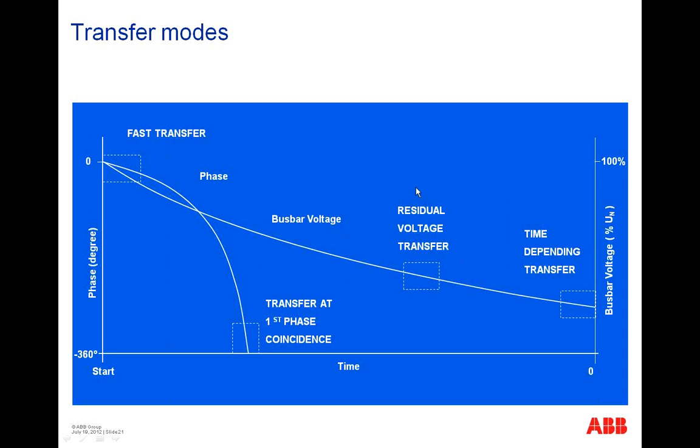At the moment the busbar is isolated, the machines are running at high speed. At this moment, they act like a generator. They are feeding energy back to the busbar while declining in speed. Both breakers are open, from the main feeder and from the standby feeder. They work as a generator, feeding some energy back to the busbar and stabilizing the voltage, but they run slower and slower. And this is what you can see here.